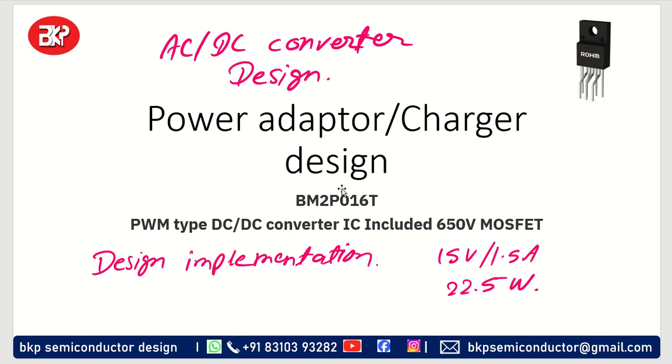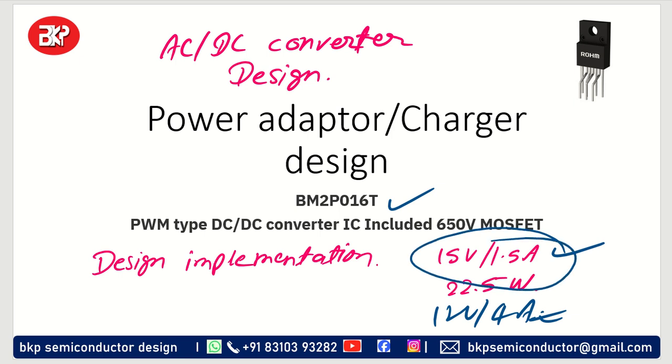Alright, so we have seen the IC design and detail, which was BM2P016T. This is the PWM controller which we are going to use to design two AC-DC converters. One will be 15 volt 1.5 ampere and another one will be 12 volt 4 ampere. So these are the two designs that we'll be doing.